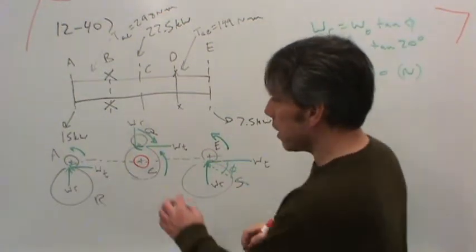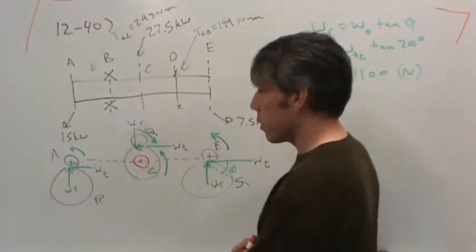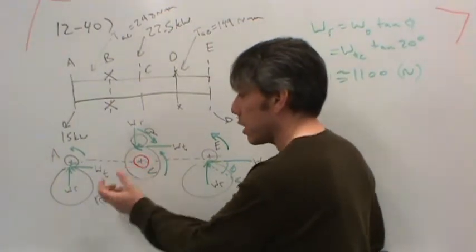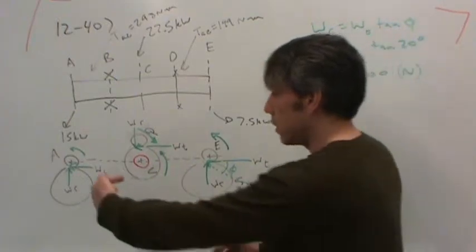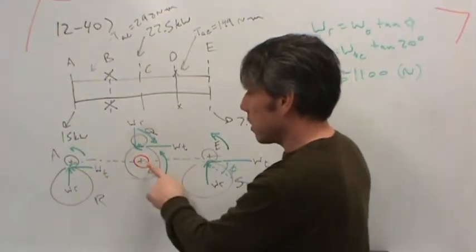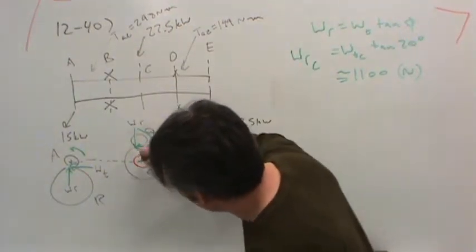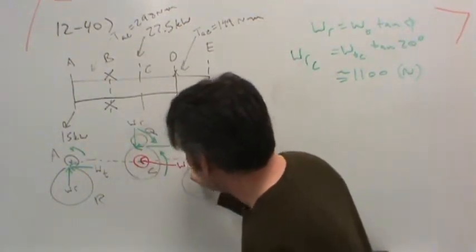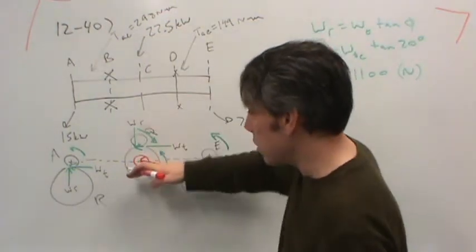If this gear should not accelerate in the X direction, how much force should the shaft put on the gear in the X direction? WT, right? And so what that means is that the force on the shaft, let me draw forces on the shaft in red, the force on the shaft is WT as well. Does that make sense? Basically, this load just gets translated down.